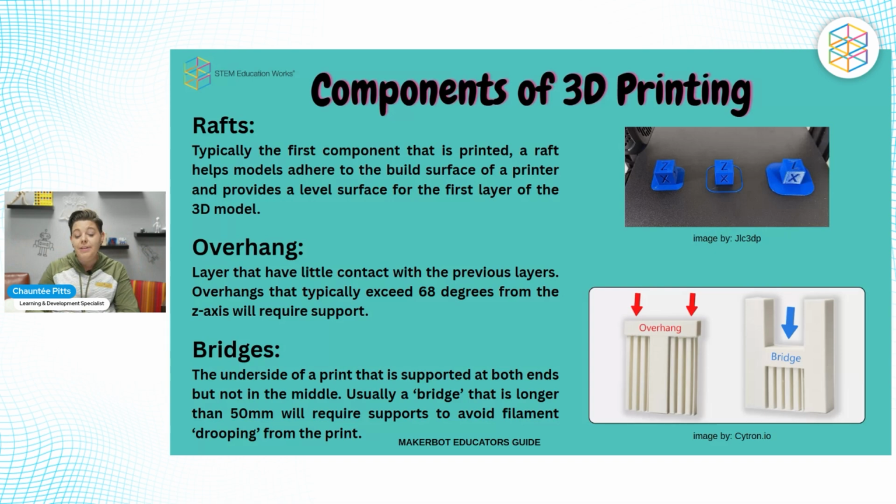But sometimes it's just a matter of the bed and the filament head not being quite at the right level, which is, you know, a thing. Yes, I know, it's very annoying. I hate it too. So with a raft, I always think about the picture I have up here. I would never put a raft under a square unless there was some purpose for it to be there, and it's a waste of filament also. So you want to consider that.